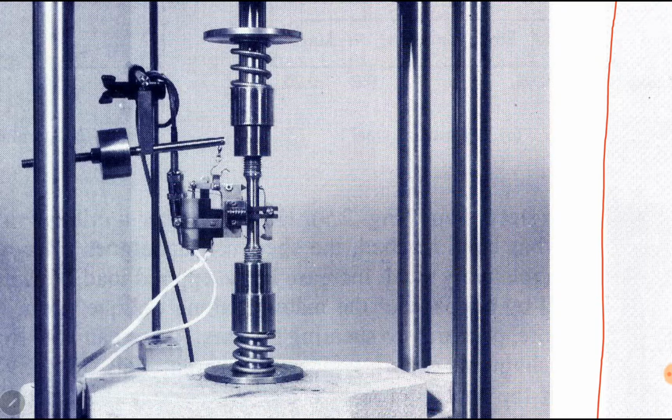and then the graph suddenly falls down, even though the strain is increasing, but the stress is noticed to decrease up to some point which is called the lower yield. The stress level decreases between upper and lower yield in ductile material. Actually, we are drawing this graph for ductile materials. This decrease in stress despite the increase in strain is due to the change in equilibrium state of the atomic structure of the material.